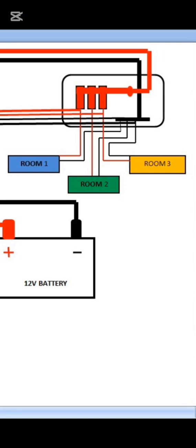Or the other way, you disconnect the wires of room 2 and room 3 from the miniatures or circuit breakers, and only connect them with the AC output of the inverter. That's another way, if you don't want to leave the connection the way it is in the diagram and turn off the switches of the circuit breakers of room 2 and room 3.